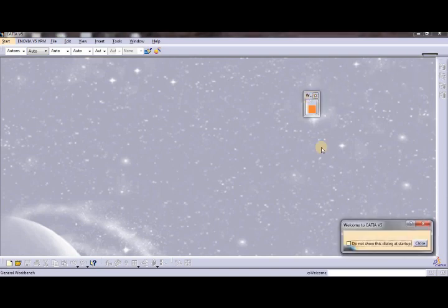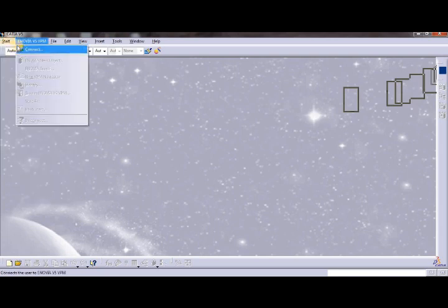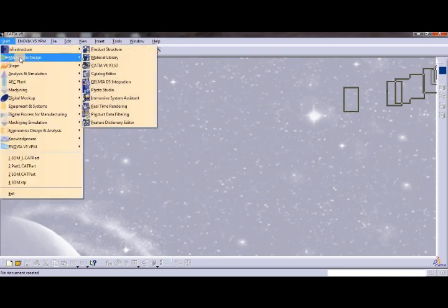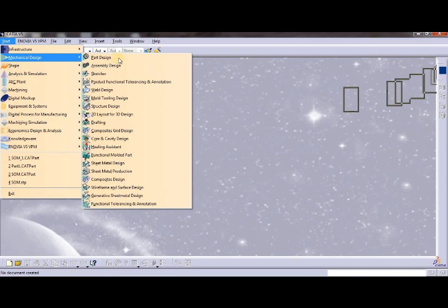And here is the workbench toolbar. If you click on this empty space, CATIA shows a welcome workbench. We have to set which workbenches we want to use. I will explain later how to set this welcome dialog box. I will place it here again. Normally we use Start, Mechanical Design, not only mechanical design but any software you want: infrastructure, mechanical design, shape design. So I will go to Part Design.